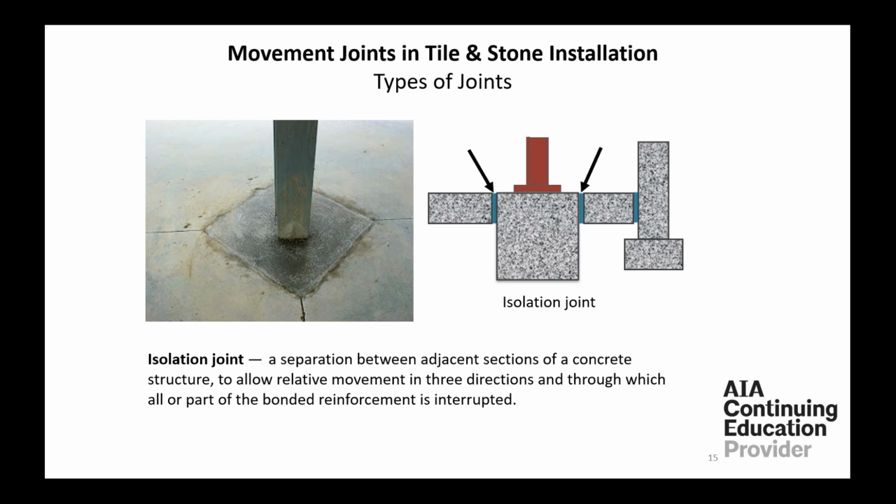As you can also see sometimes where a slab runs into a wall, they could also be separated entirely. Or for that matter, in residential, where we used to see it a lot, was when it ran into a footing, and the footing was higher than the slab. So they are intended to move, but not necessarily create stresses on the slab next to it. But can't stress, this is truly an expansion joint. Call it isolation, but it's an expansion joint.